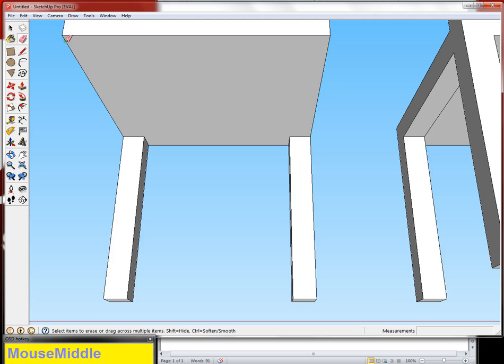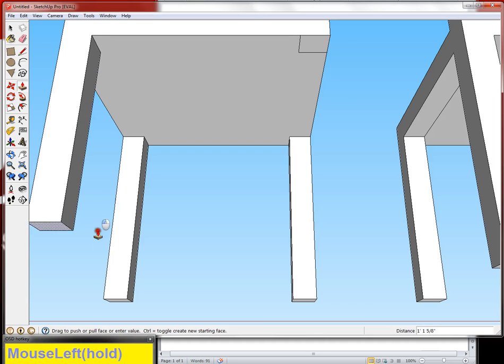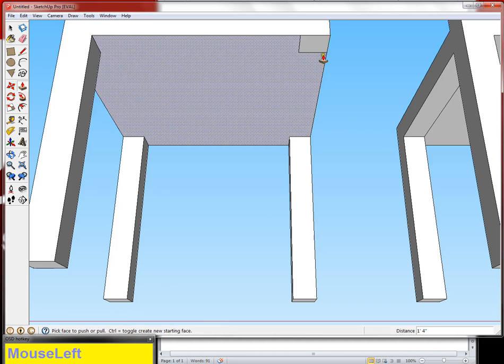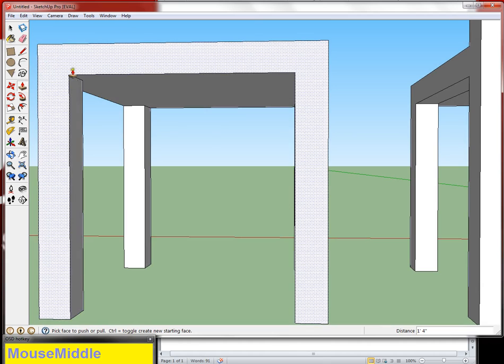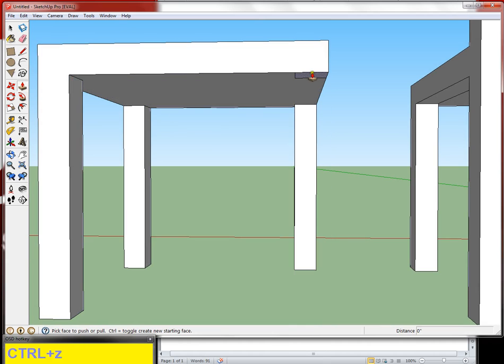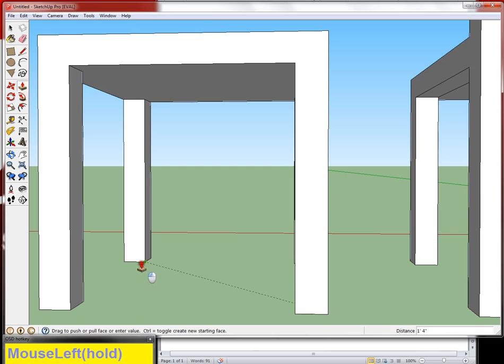I am going to make 2 legs on the back, so I'm going to use the rectangle tool, anchor in the corner, pull in the general direction of the square that I want to make, and then go 2, 2, enter. Do the same thing over here, 2, 2, enter. Okay? Now I'm going to grab the push-pull tool and pull and inference the other legs. I'm making sure that my view is very specific. If I did this, I would be able to see this and I would be able to pull it, but I can't easily inference the bottom of another chair.